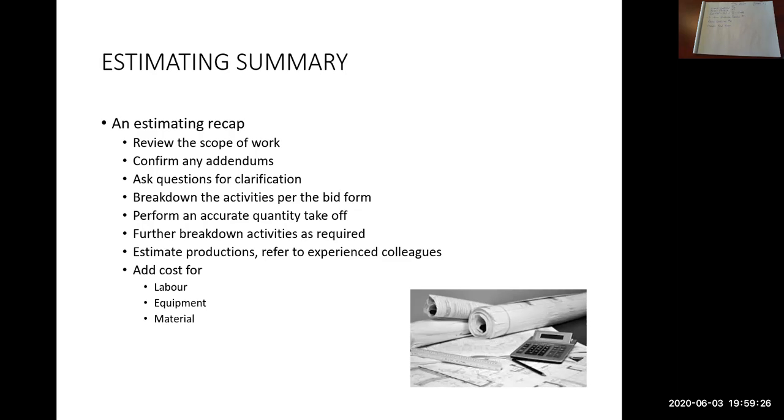They can give you the lineal meters per hour of pipe installation, depending on pipe size, pipe depth, existing utilities in the ground. How fast you can place your embankment fill to build up that 4-meter high embankment for your bridge approaches. So those types of things will likely be provided to you, that hopefully you'll learn as you're going, and you'll retain that information for future estimates.